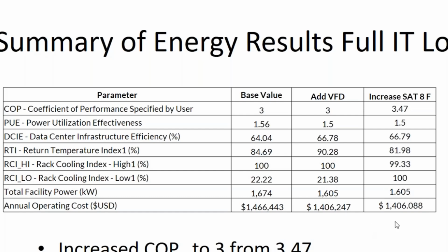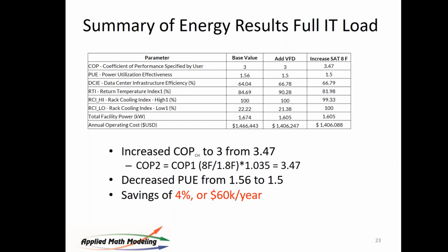So now this makes an assumption that we didn't get more efficiency out of the chiller, which may happen, particularly if it's an economizer. If it's an economizer chiller and you raise the supply air temp by 8 degrees, it widens the window of time that the economizer gets to operate. And that may change your annual COP quite dramatically. But you can see here a case where, all things being considered and no economizer in play, that you've reached an optimal point.